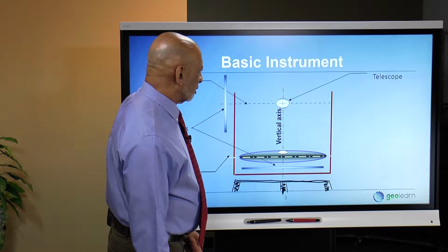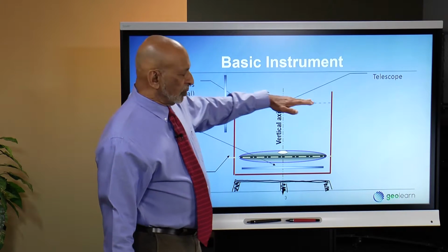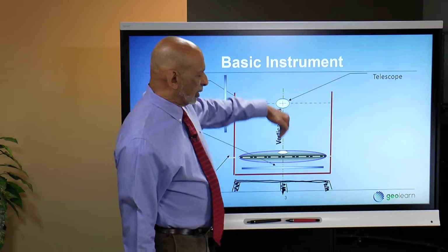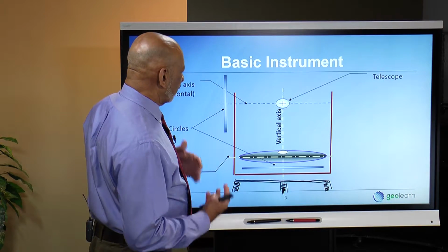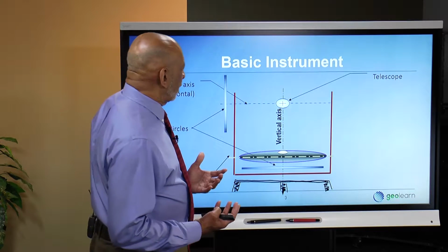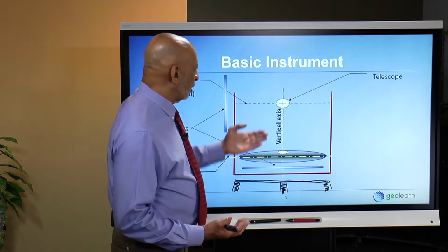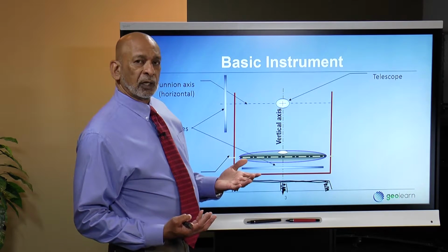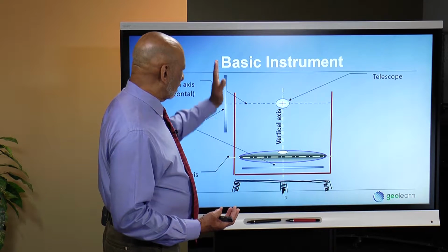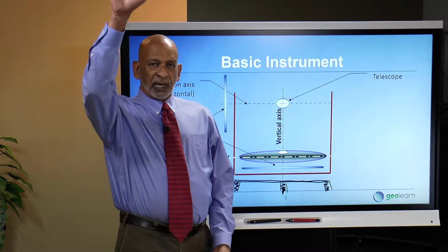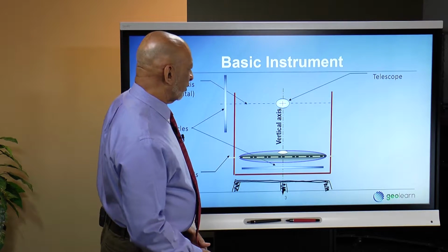a horizontal angle. We also have a horizontal axis, which is made in the factory to be perpendicular to the mechanical vertical axis of the instrument. And again, by definition, if everything is properly aligned, namely that you properly centered and adjusted the level vial, then the horizontal axis is going to be truly horizontal as well. And then mounted on that axis is the vertical circle, so that as we raise and lower the telescope, we can now measure angles in the vertical plane.